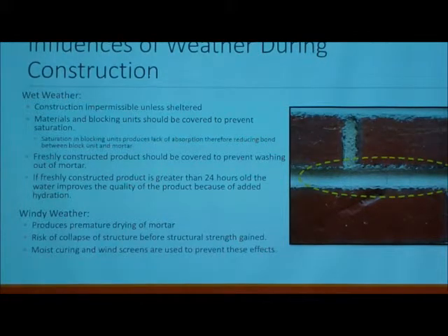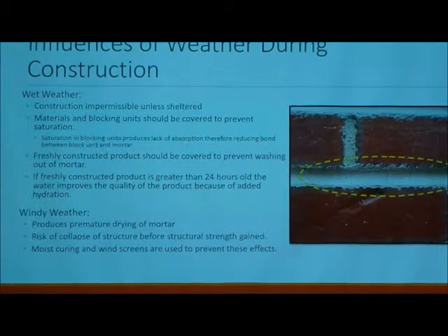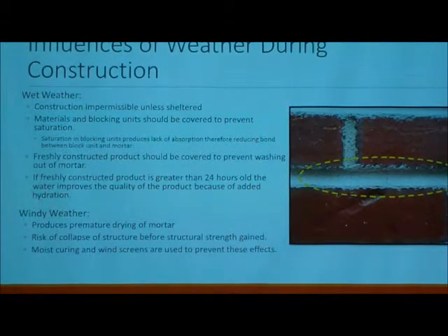Once a product is greater than 24 hours old, so if you go out and lay a block, let it sit there for 24 hours and then the rainstorm comes, it actually helps with the hydration process. So it's permissible to uncover those units after that in order to help hydration.